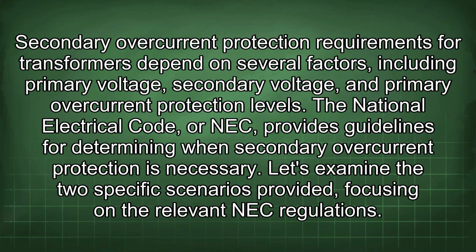Secondary overcurrent protection requirements for transformers depend on several factors, including primary voltage, secondary voltage, and primary overcurrent protection levels. The National Electrical Code, or NEC, provides guidelines for determining when secondary overcurrent protection is necessary. Let's examine the two specific scenarios provided, focusing on the relevant NEC regulations.